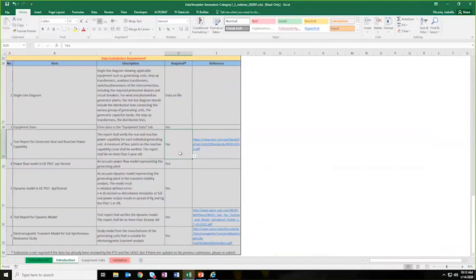I think if we say you should provide a test report, then you should do the test. Yeah, so just to clarify, Mark, are you saying that your unit was not large enough to qualify as NERC EES or to qualify for Mod 26 and 27 testing? No, so in Mod 26 and 27, the 5% net capacity factor over the last 3 years, if it doesn't meet that threshold, then under that exception you don't have to verify the model under requirement 2. So we have a couple of units where that's the case, where the units are not run that often and therefore don't meet that 5% threshold.